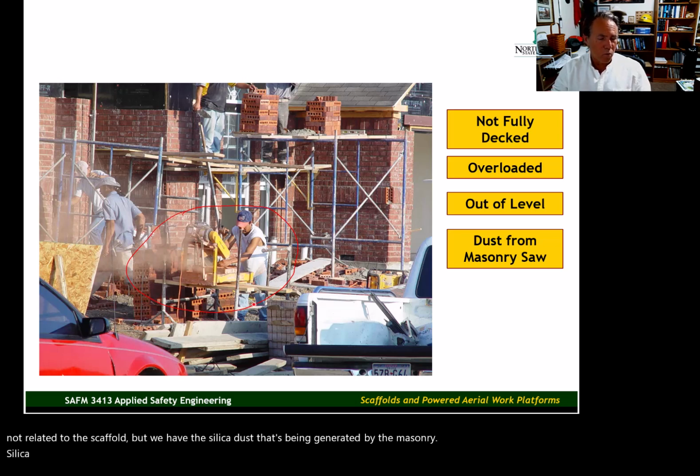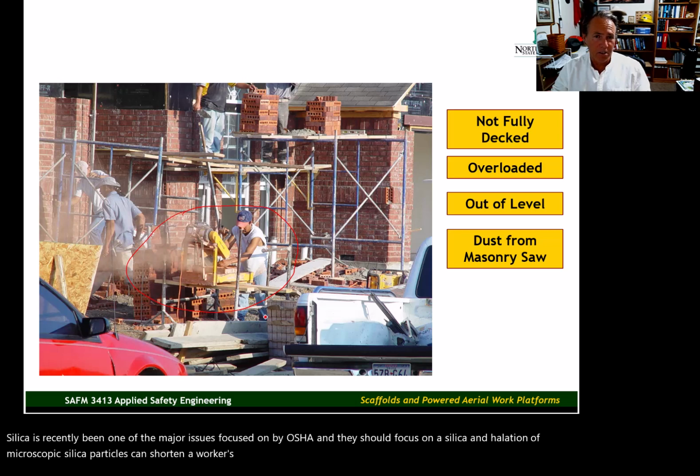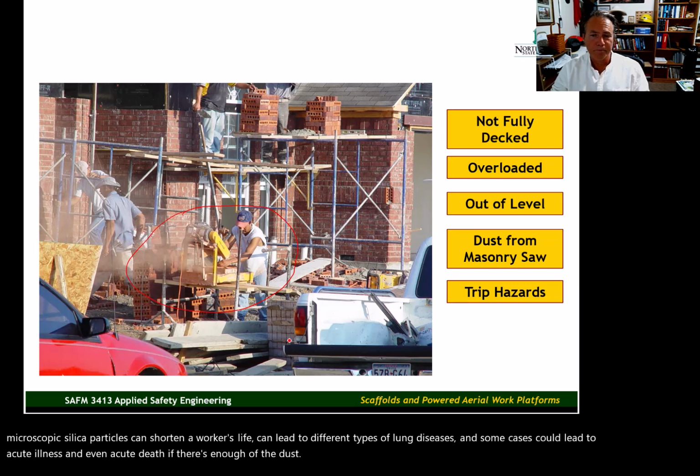Silica has recently been one of the major issues focused on by OSHA, and they should focus on it. Inhalation of microscopic silica particles can shorten a worker's life and can lead to different types of lung diseases. In some cases, it could lead to acute illness and even death if enough of the dust is inhaled.